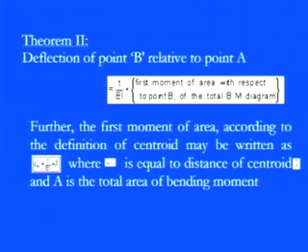In the first case, the slope is equal to 1 by EI times the total bending moment area, just the area. But if you want to calculate the deflection, delta was equal to M dx divided by EI into x, so it converted into the first moment of area.